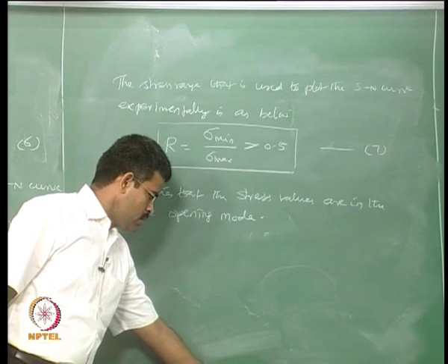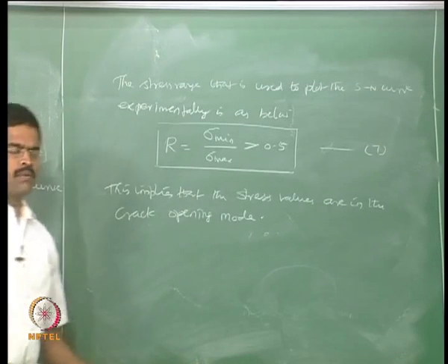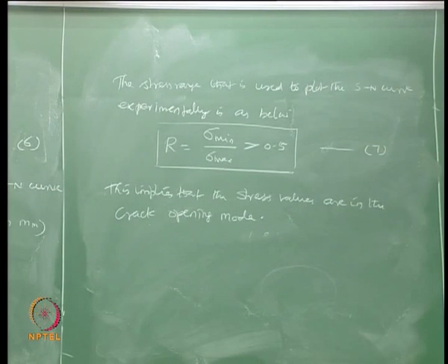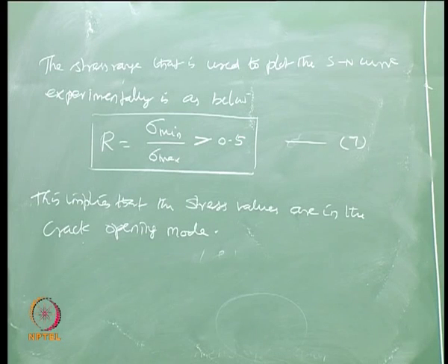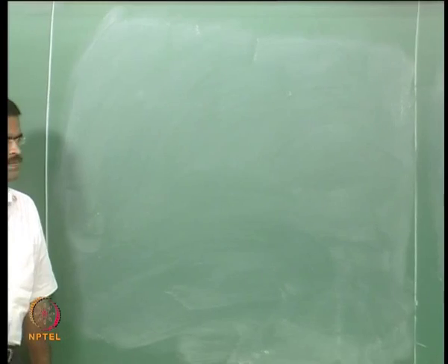Having understood the stress-strain, I would say the SN curves are plotted experimentally. The shape of the specimen, type of the specimen, shape of the weld, and thickness of the reference member all influence the SN curve.